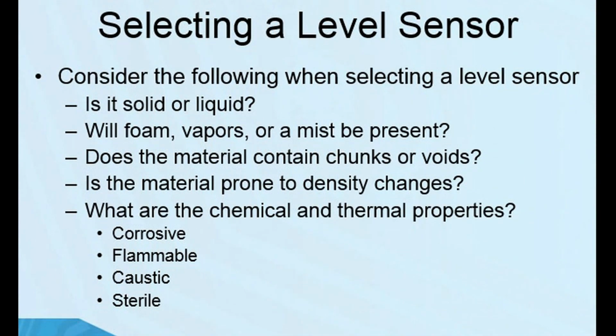Here's a chart to help you select what type of sensor you need for measuring level. And of course, you have to decide, is the liquid explosive? Is it a solid? Is it a liquid? Does it form vapors, etc.?